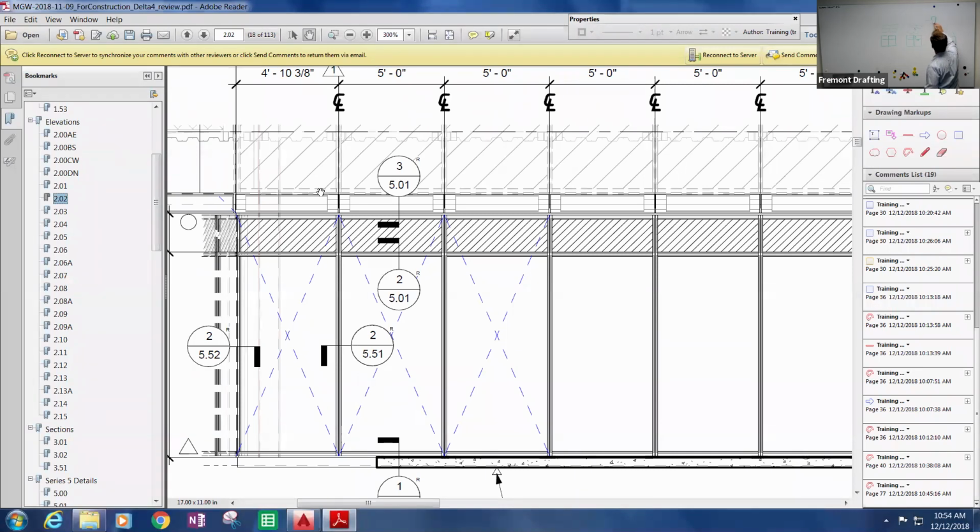So this is my precast, let's say, and then here's my window mullion. And so how we do it is we put an angle here. It's attached to the mullion. And so now this element here, our window mullion, can rack, and this precast element can translate. But it's in front of our windows so that it won't hit.